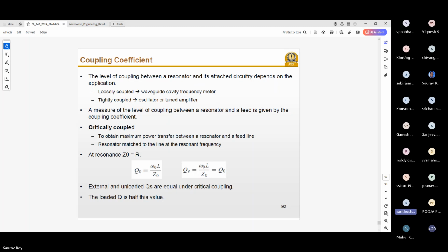We are using one module, actually down conversion only. From 2 to 18 GHz we are down converting to 140 to 240 megahertz. Like that we are doing down converting. Okay, in that lumped filters also we are using, sir.